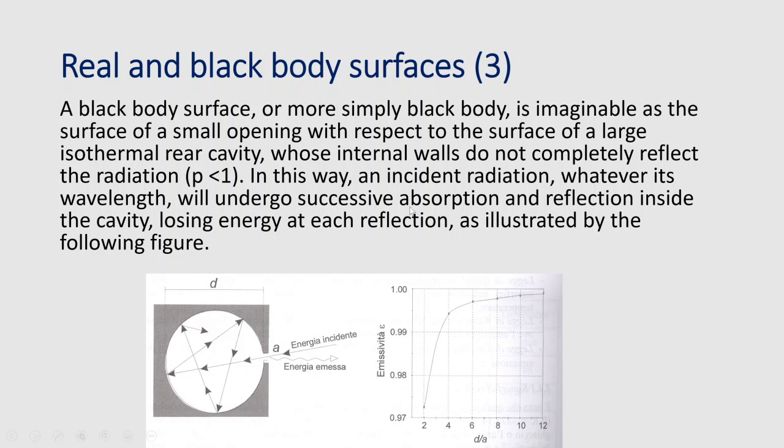That means that when you have incident radiation coming in through the cavity from these little openings that we have here, this cavity is not really a black body, but something that is going to simulate a black body. Being not a black body, this inner surface is not absorbing all the energy, all right? So part of this energy will be reflected in another direction, like here.